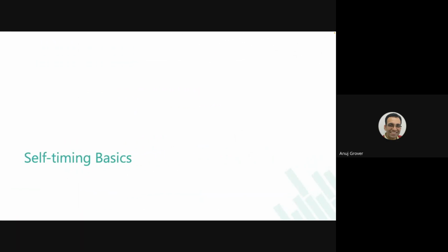And now we talk about self-timing. See, हमने अभी तक हमेशा ये, we have already always said that when sufficient differential will appear, the sense amplifier should turn on. अरे भाई, it's not going to happen अपने आप. You have to play that magic. Okay? You have to tell when to turn on the sense amplifier. Sense amplifier will turn on at some point of time, yes. But you have to ensure that the time when you turn the sense amplifier on is safe.